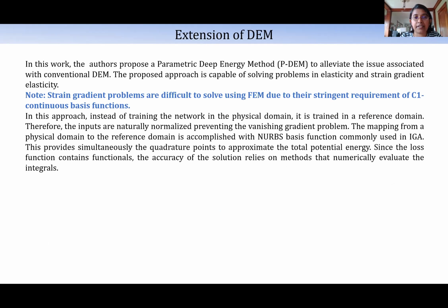To alleviate that, the authors have proposed a parametric deep energy method approach, where the proposed approach is capable of solving problems in elasticity and strain gradient elasticity. Now, why strain gradient elasticity is so much focused here is because strain gradient problems are difficult to solve using the finite element method due to the stringent requirement of C1 continuous basis functions. In this approach, instead of training the network in the physical domain, it is trained on a parametric domain, which is also referred to as the reference domain. Therefore, the inputs are naturally normalized, preventing the vanishing gradient problem.